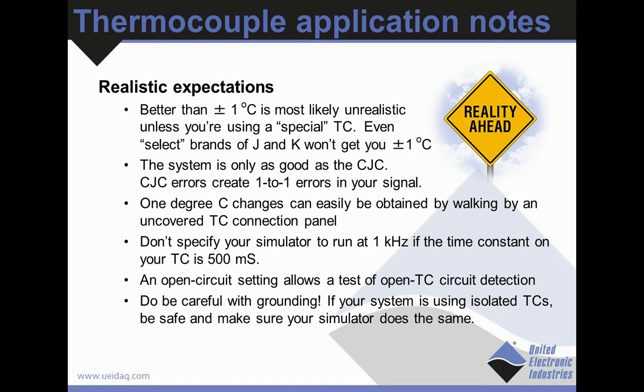Other things that you'll want to include, especially in a SIL, is an open circuit setting on the thermocouple simulator board, because thermocouples do open now and then, and it's important for your flight control system to be able to know when that happened and know how to behave accordingly, not assume that things have gotten too hot or too cold. And be a little careful with grounding. If your system is using isolated grounds, you should certainly consider using an isolated output board. And even to reduce noise, we'd always recommend, if you can, use an isolated thermocouple simulator board.